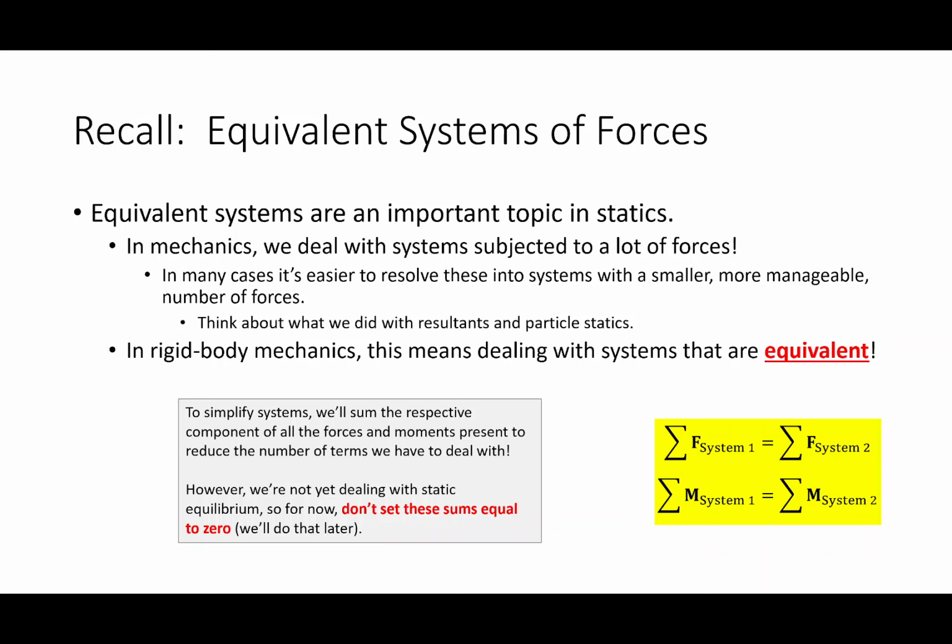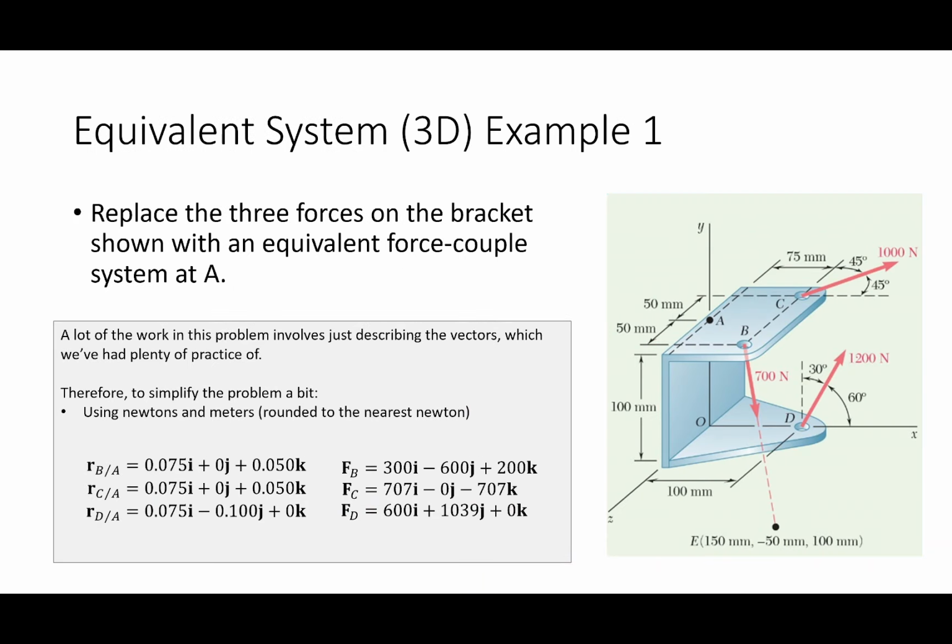We have a very particular name for those forces in statics. We call those reactions. Okay? Every action has an equal and opposite reaction, right? So the idea behind what we're going to start on Friday is if I have a beam with a bunch of loads on it, what are the forces that are required to keep the beam in equilibrium? Those are reaction forces. We're going to talk about that on Friday. Today what we're going to do is 3D land, and I've got two examples.